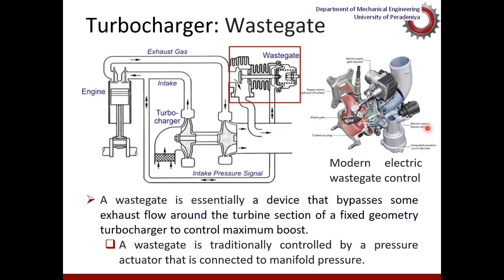So in certain modern engines, in certain low speed and low load operating conditions, the turbocharger is shut down, particularly petrol engines. And whenever the engine boosting is required for the acceleration and running at high speeds and pulling large loads, the wastegate is controlled such that the turbo boosting is enabled and required power could be produced.